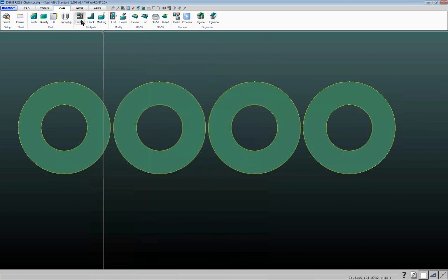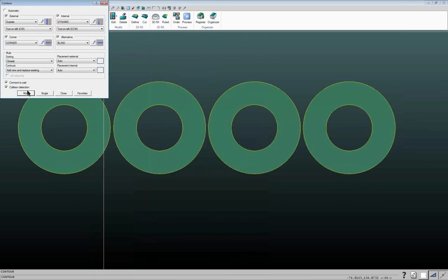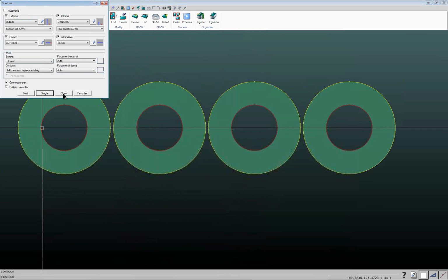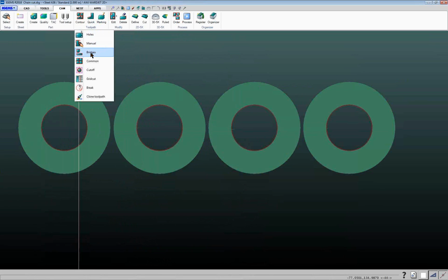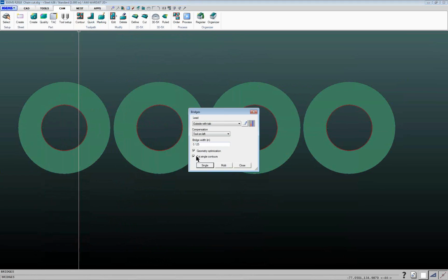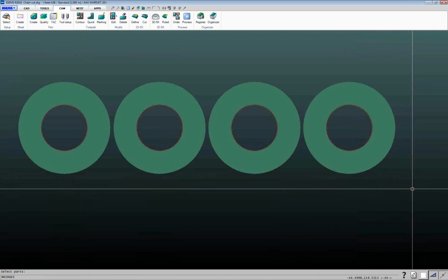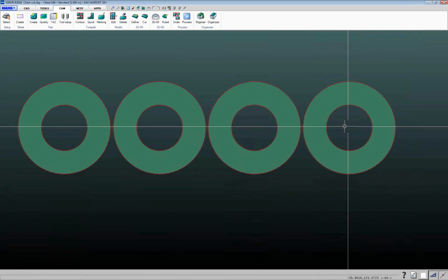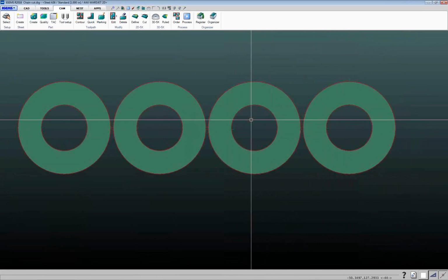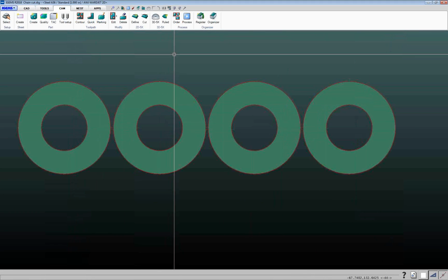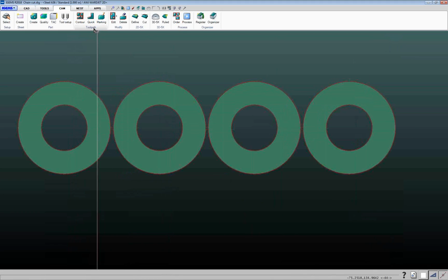If we go back into bridges, and I would prefer to have done my own normal single or my normal internal lead-in command, then I can just do it like this, and then come back, go into my bridges command, uncheck the cut singles contour box, and do my multi again. Then in this case, it's going to use what I wanted for my inside leads, and then do my chain cut for my outside cut. So that's one way of doing that.